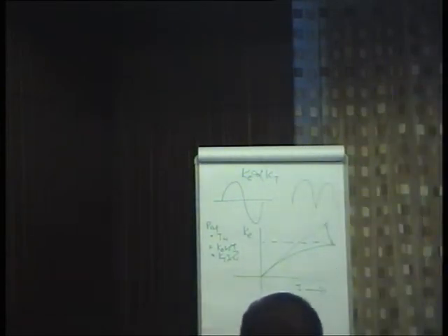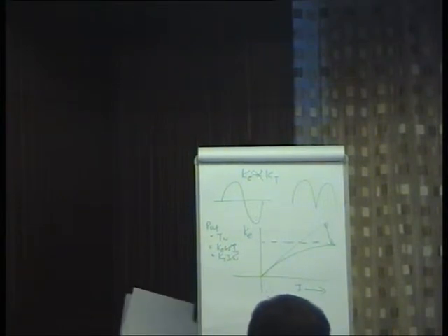So this table here, the E table, is a voltage source. Basically, we make a table based on FEA values, finite element analysis. Let's say we display this value only. So this is the table. It's a big table. Table of what? Table of saturation: how K_E and K_T saturate with current.